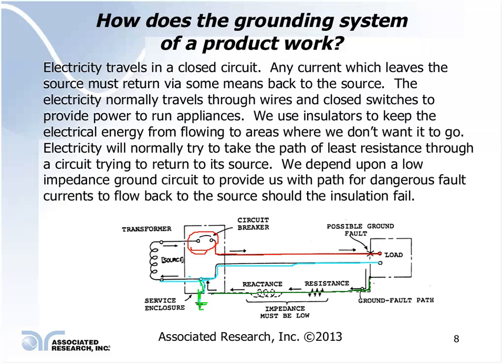You don't want the ground circuit to open up. So it's got to be a low enough impedance to allow enough current to flow to cause this fuse or circuit breaker to open up. Ohm's law: voltage is equal to current times resistance. In order to have the fuse or circuit breaker open up, let's say this is a 15 amp breaker, it can carry 30 amps of current for 2 minutes.